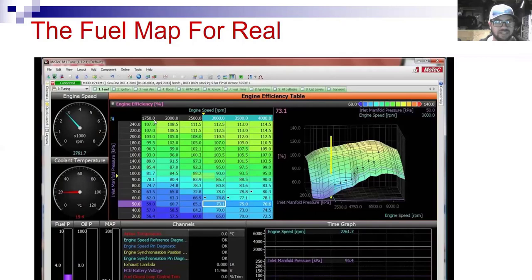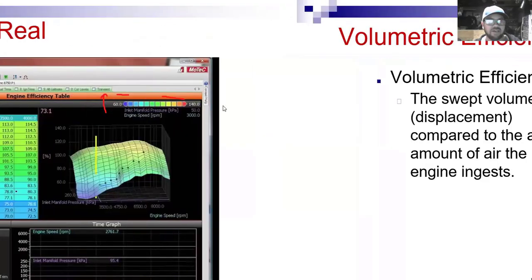You also have tables like this that you would adjust in this software for not only your fuel, but if you look at some of these different things, and again, we do this in the 325 class, we got our fuel, but look, there's tables for ignition, there's tables for boost and RPM limits and NOx sense. So there's multiple tables that as the EFI tuner, you get to adjust to make that engine run exactly how you want it to run, which is really, really fun and interesting. And that's why on a lot of vehicles, you can unlock a lot of power with the right tune, if you will. So, all right, but moving forward.